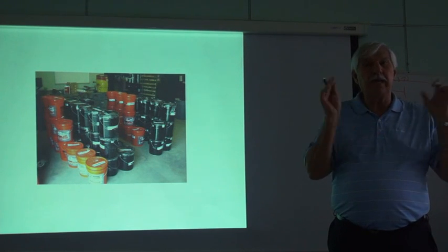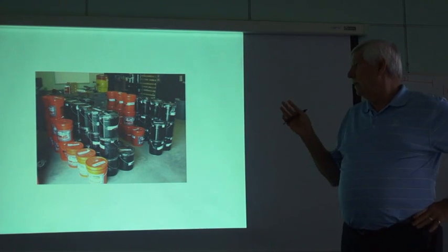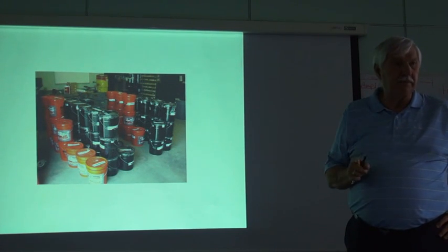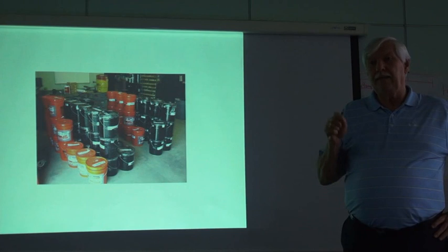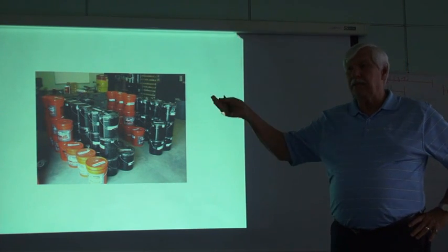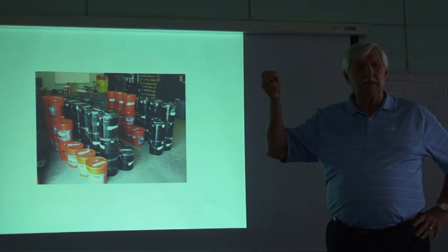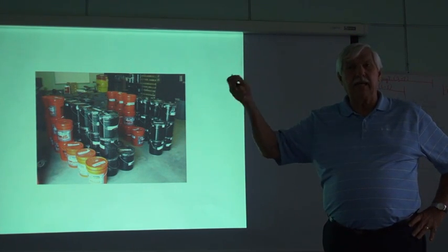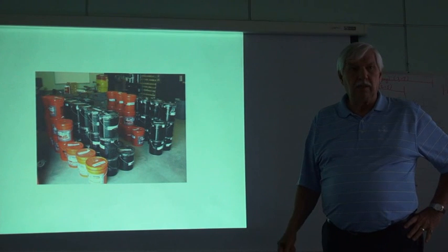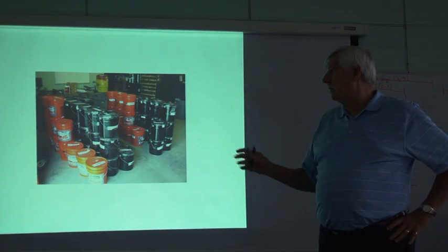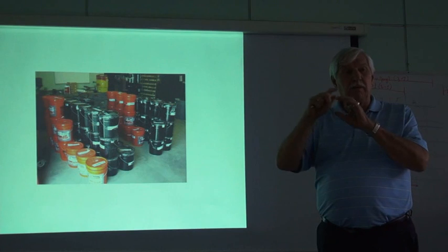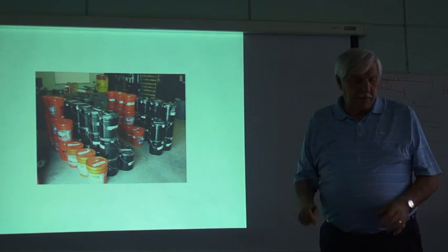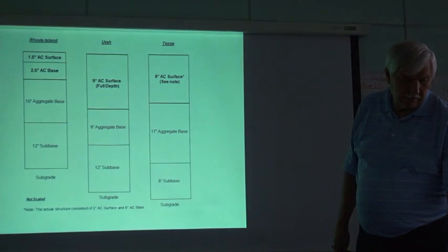So we've taken 3 actual field projects and sent all the materials. We need raw materials to do the job mix formula master curve. And then as the contractor paves in a given day, we'll take material for 4 sublots for every lot, or every day that he does it. So what we're doing is having enough material on 3 projects to do a job mix master curve as well as the effective E's to check and validate the system.